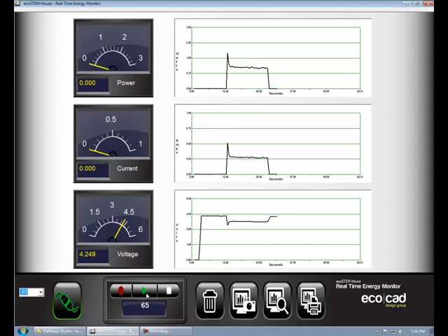So let's continue. Here we'll turn on the load again. We'll stop it. And if my fingers were quick enough, I'd have picked up the peak there. But here we are just after the peak of the motor fan turning on. And here we have frozen the power at 1.02 watts, the current at 0.274 amps, and our voltage at 3.722 volts.